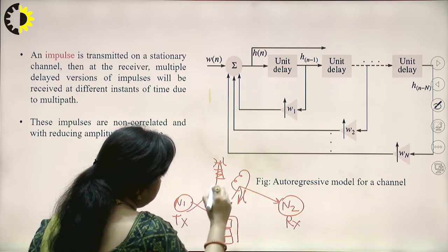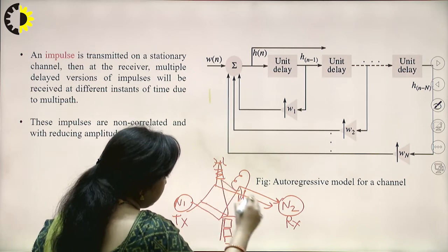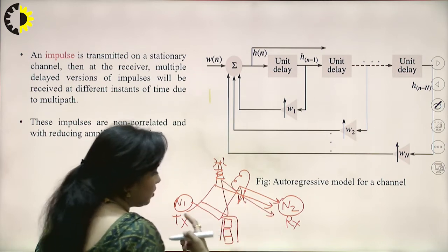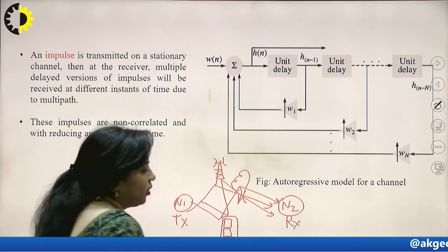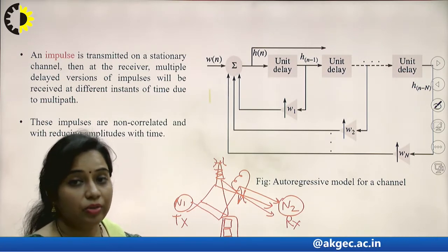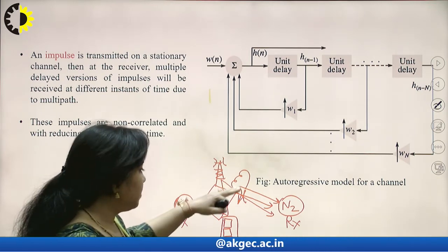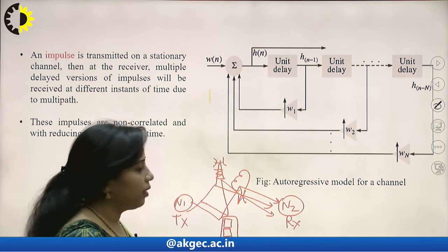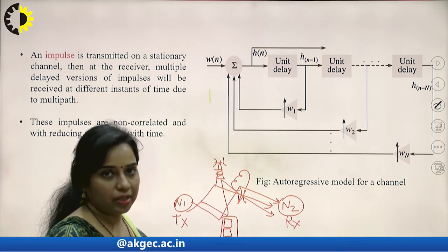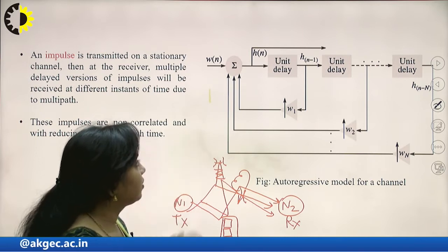This is the possibility, maybe 2 hops, maybe 3 hops, maybe a single hop, but there is very little probability that the signal will be delivered directly to the receiver, meaning there will be no multipath propagation. So since it is going to follow 2-3 paths because it is multipath propagation, all the signals which are received will be added at the receiver side.